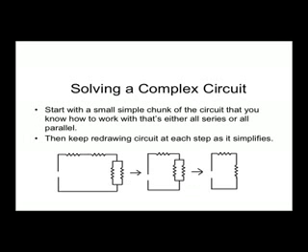So in this case, now we can add to this. This is called a complex circuit, also known as a series parallel circuit. A series parallel circuit is a combination circuit containing loads in both series and parallel. Complex circuits are extremely widely used in a lot of the control circuits in the industry today. To solve a complex circuit, start with a small simple chunk of the circuit that you know how to work, either series or all parallel. Keep redrawing the circuit each step as it simplifies.